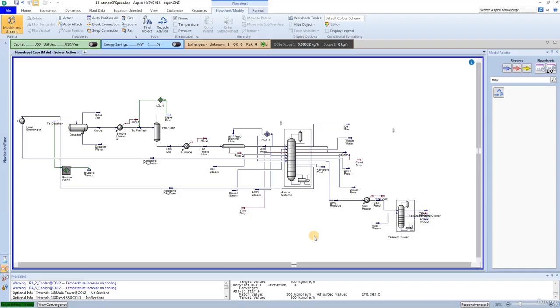Task 5. Energy stream heat integration. Heat integration in Aspen HYSYS can also be attained using energy streams rather than material streams. The benefit to using energy streams is that the flowsheet typically will not require iterative calculation to solve. Therefore, no recycles and no initial estimates are required. These situations are typically much easier for the HYSYS user to configure. Use the atmospheric gas oil pump around from the atmospheric column to heat the crude oil at the entrance of the preheat train to recover as much heat as possible.